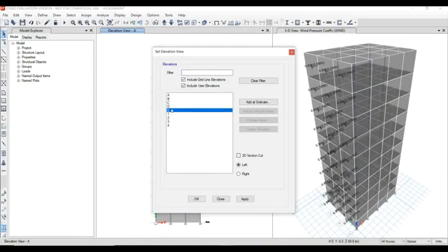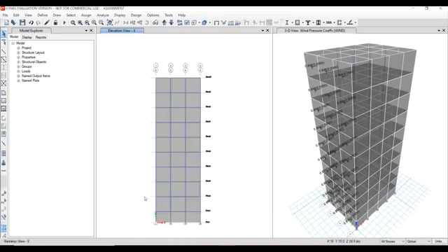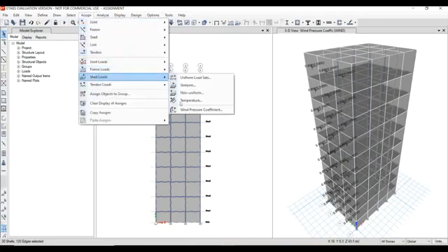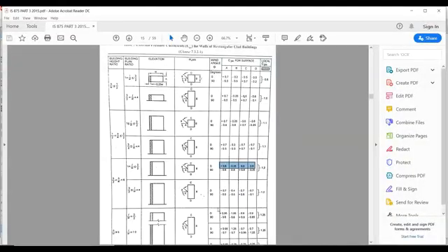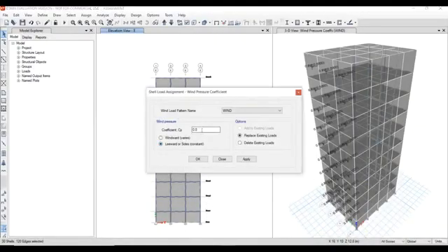Now we need to select the elevation of the last face so that the wind will be facing on it. This is elevation E. So make sure that all stories are selected. Select every story shell. Now assign the load. Assign shell load, wind pressure coefficient, which we already got, minus 0.25 in leeward direction. Click leeward, minus 0.25. Apply.